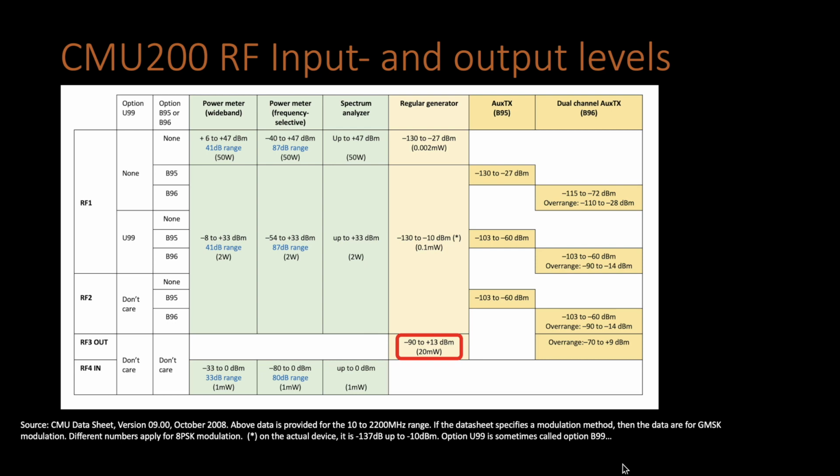Okay, so far for the input handling possibilities. Well, maybe I should add here that the RF4 input is much more sensitive. There's an extra amplification stage at that one. It seems to deal a little bit with the noise floor as well, but we can go all the way to minus 80 dB measurements here.